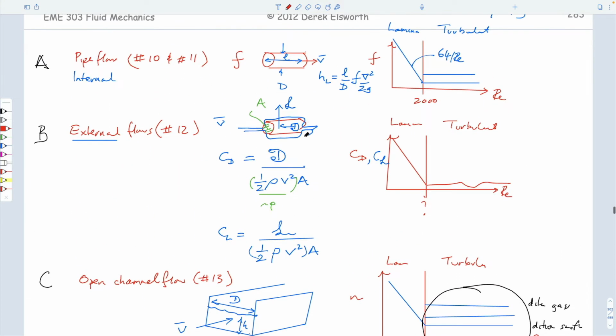We made the case that it's really this interplay between Reynolds number and Euler number, defined here as a friction factor but equivalent to an Euler number, that defines the behavior for flow in pipes, where we're interested in the drag on the fluid by the pipe; on flow around objects, like a wind turbine blade, where we're interested in the shear stress applied on the blade by the fluid.